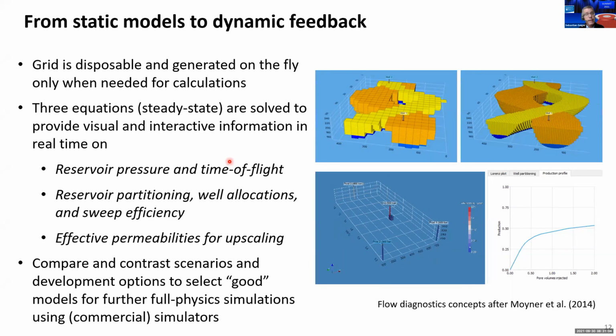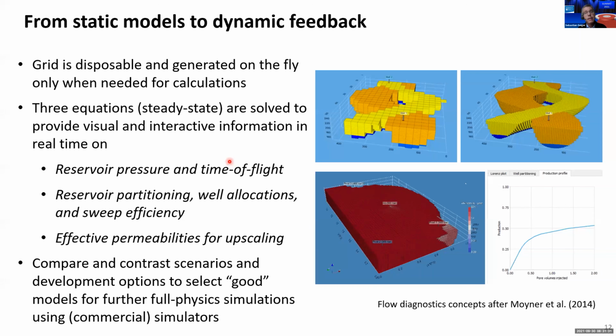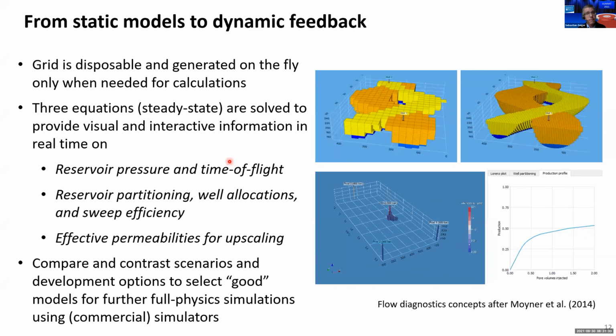So we can start selecting good, geologically meaningful models that we want to study further with full-physics simulations using commercial simulators such as CMG. We simplify a lot of the physics here. Eric talked about compositional modeling, so then you add the compositional modeling, the thermal modeling, black oil, etc., whatever we need to do to get the physical detail right once we've screened the initial geological heterogeneity and looked at different geological concepts.